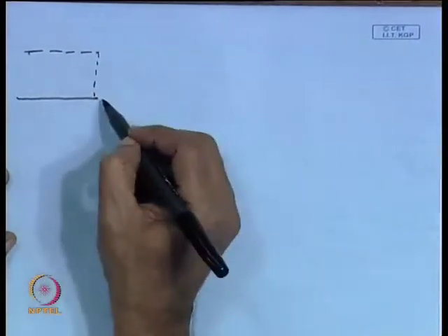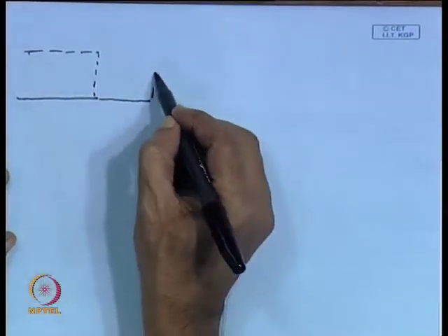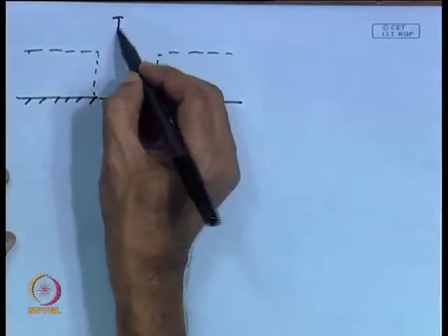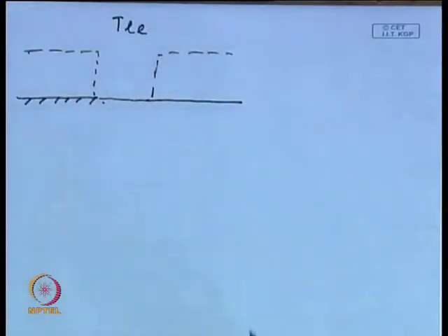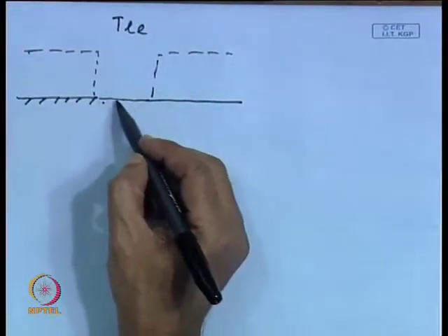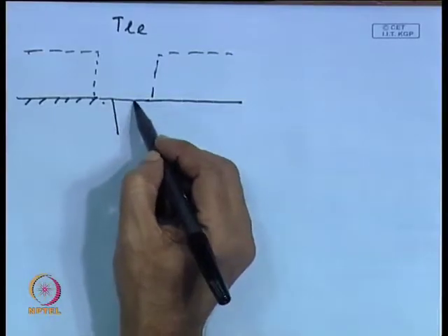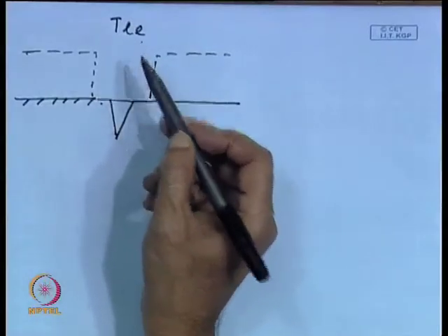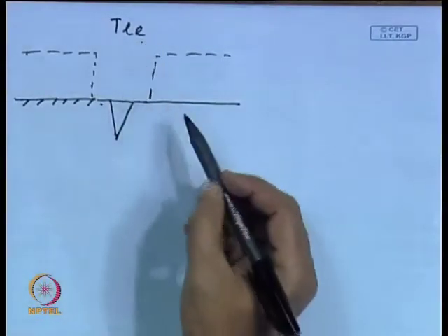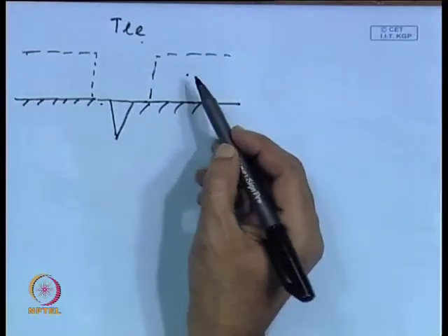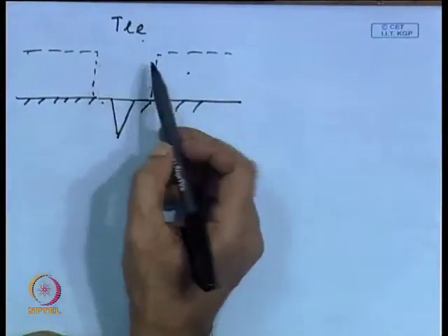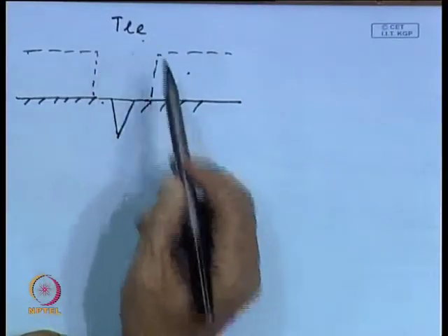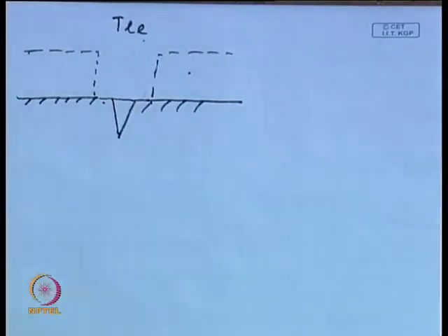You have to remember our earlier phenomenological explanation, that this is your T L E or T infinity. Now, if the site has to be active, then after the bubble has departed, we have a temperature which is lower compared to the wall temperature, but that could not be too low, and here we should have a higher temperature liquid. This should be replenished by a higher temperature liquid. So, that is what has been told.